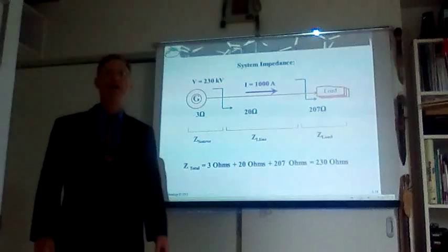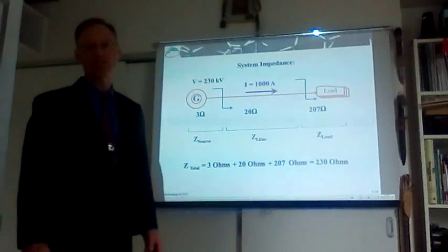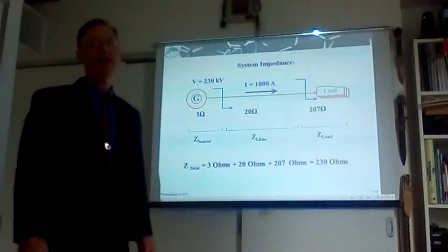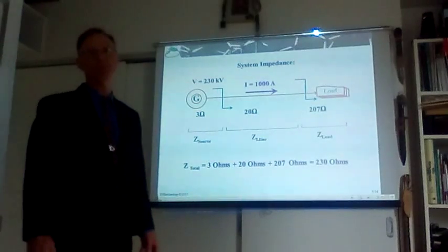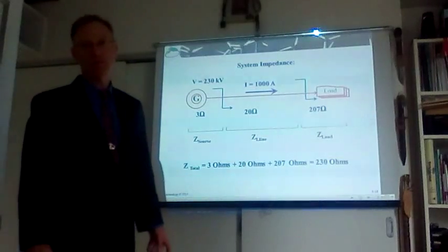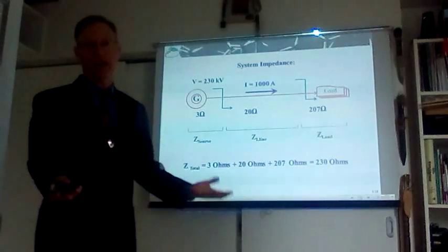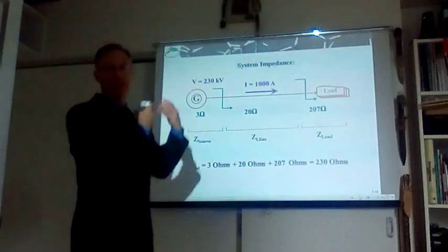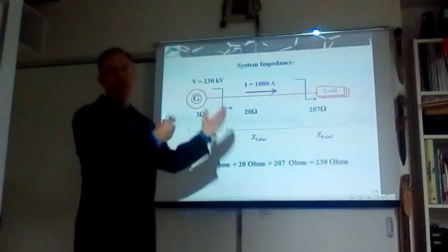The protection relay will evaluate how much is the drop and how fast is the drop. Based on that, it will conclude that it is a fault and trip. That trip is our protection on the line.